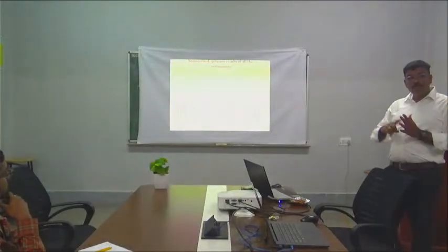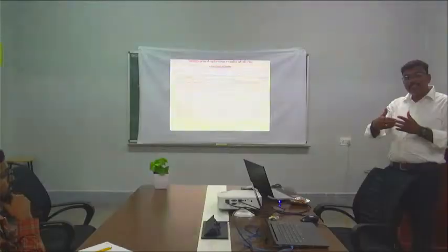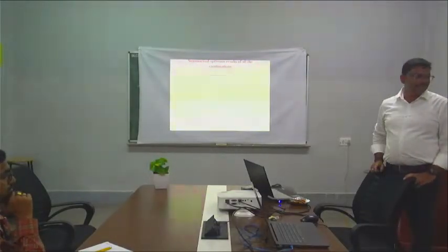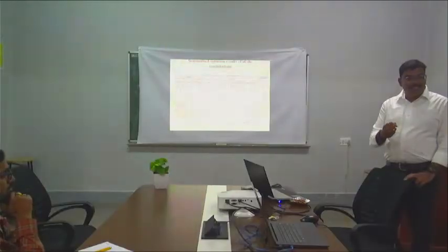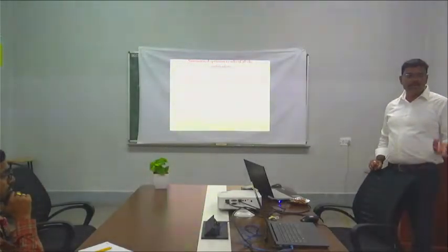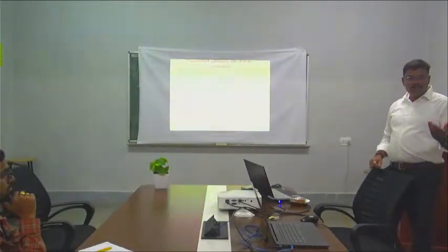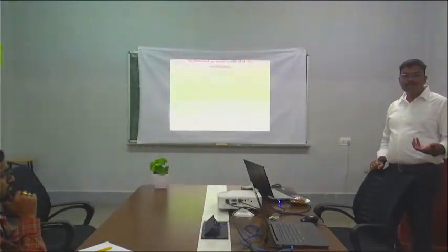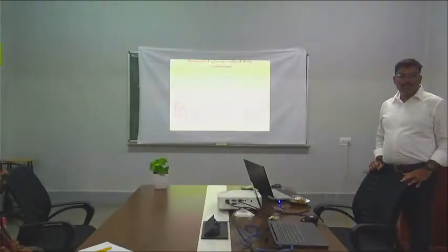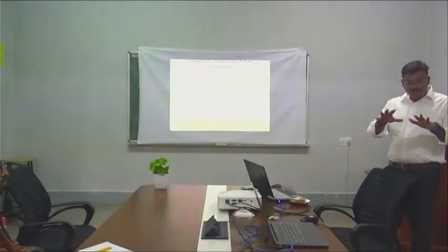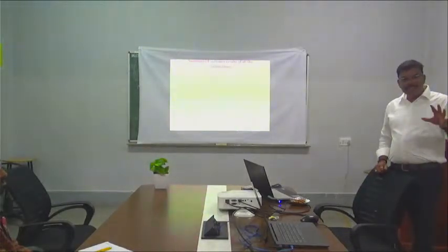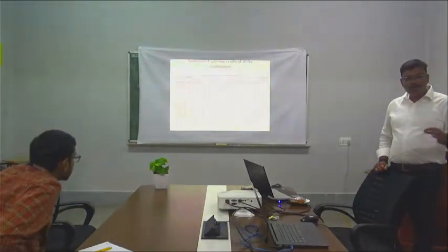But the input parameters for that particular system are data integrated through NASA. The performance yield is calculated based on the input data received from the NASA methodology, because we are giving irradiation. I showed you one graph. Irradiation we are giving, temperature we are giving, wind velocity. All those things are not decided and given by us. We have taken them for that particular latitude and longitude. That means the input is correct. Sizing is done by the optimization algorithm, the Homer optimization algorithm.